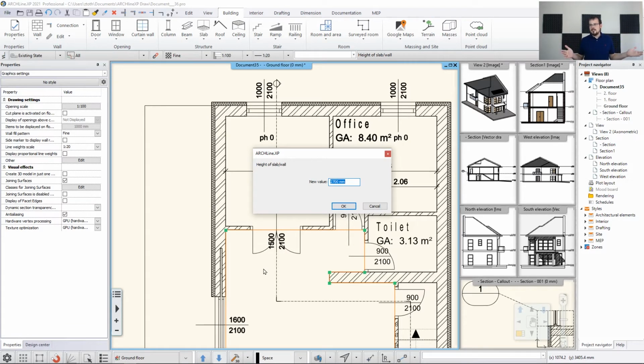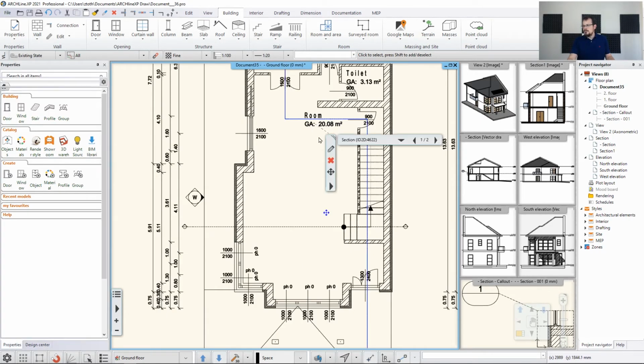Now this is important, because when you create a room and area based on an automated method, the software knows that these are the walls and the ceiling is all the way there, so it can calculate the values by itself. But in this case, the software is not able to rely on existing information. So you need to tell the software what the wall height is, which is 2,700 millimeters. Let's just hit OK. And now I have one room over here.